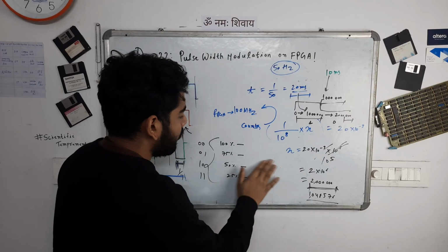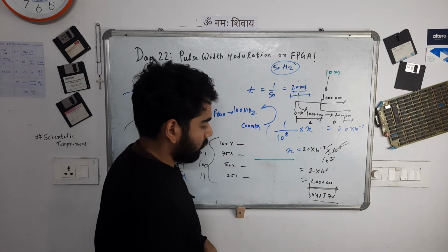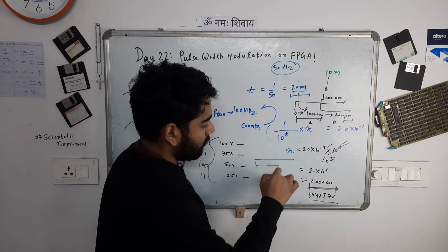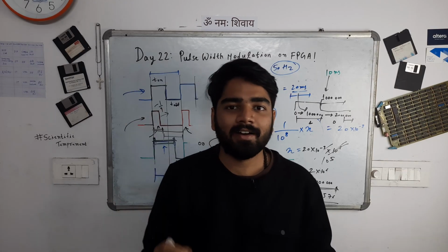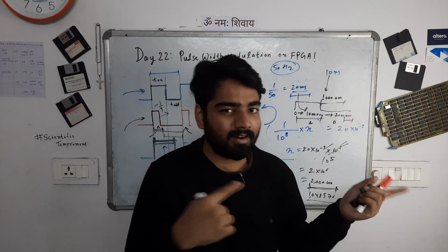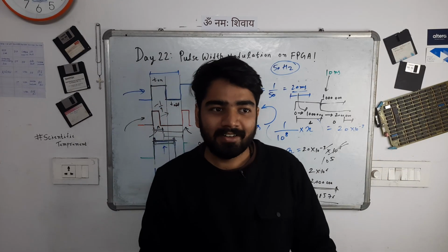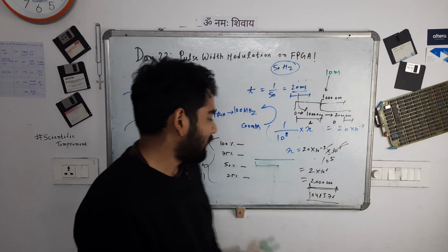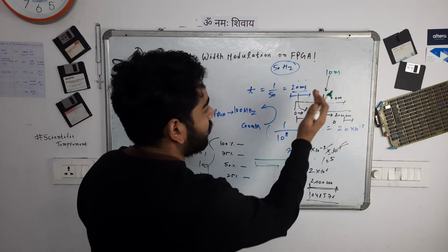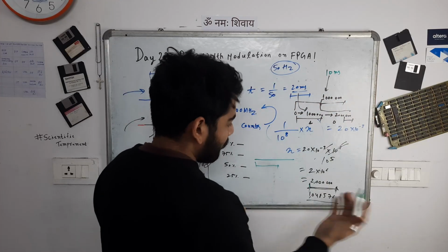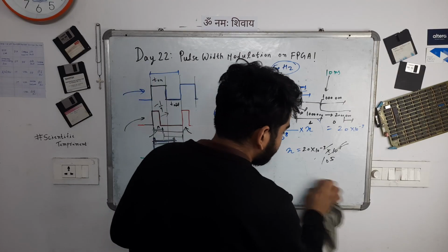Okay, let's talk about 100% duty cycle. 100% duty cycle means that the signal is constantly on, right? It is on for 100% of the time. Our counter is counting up from 0 to 2 million, right? So if we have our output as high until the counter reaches 2 million, we are going to have a 100% duty cycle, because the counter will reach 2 million and will again go back to 0, right? So if we want our signal at 100%, we can simply set that mark of the counter at 2 million itself, right? That is the intuition. Let's go and see this 75%, okay?